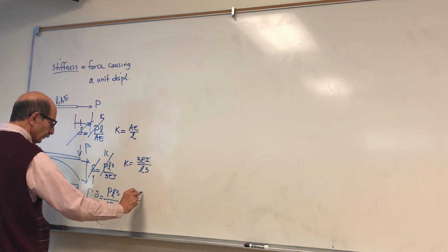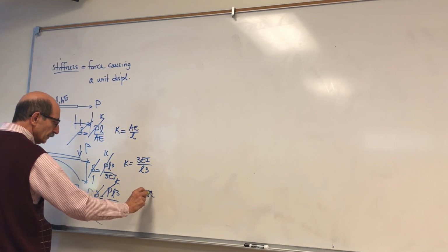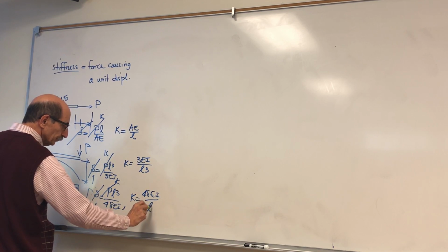So the stiffness would be, if this is 1, 48EI over L cubed.